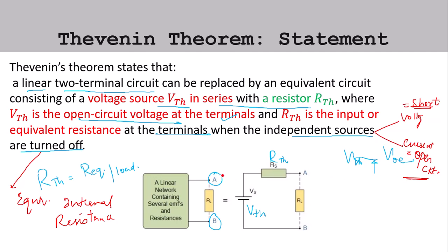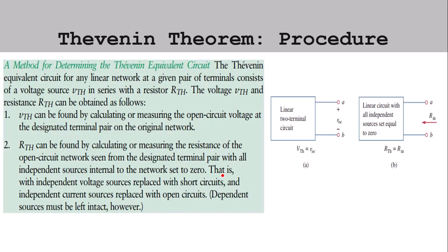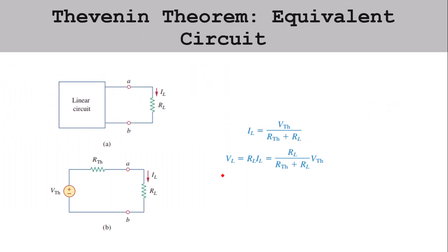So this is the definition of Thevenin theorem, and the same thing is given in the slides which are being provided here. Now ultimately, once we find the VTH and RTH, then we can connect any kind of load that is given in the circuit, and we can find the value of IL.